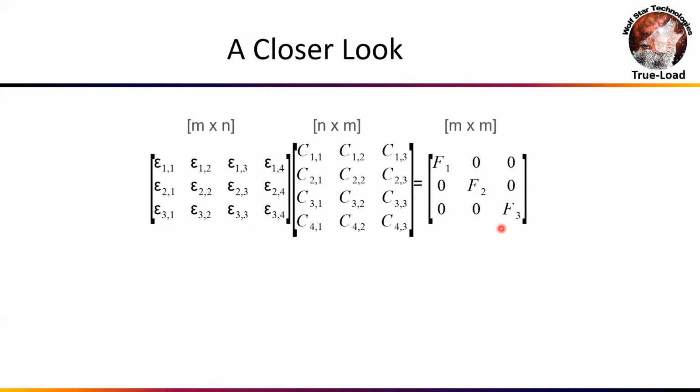Let's say we had a plate that was bolted to a structure. This is a square plate bolted down at 4 locations, the 4 corners. We solved the plate for its mode shapes, so we got the modes for the structure. And then where it's bolted down at the 4 locations, we put XYZ unit displacements on our FEA model. And we laid strain gauges for all of that, the mode shapes plus the unit displacements.